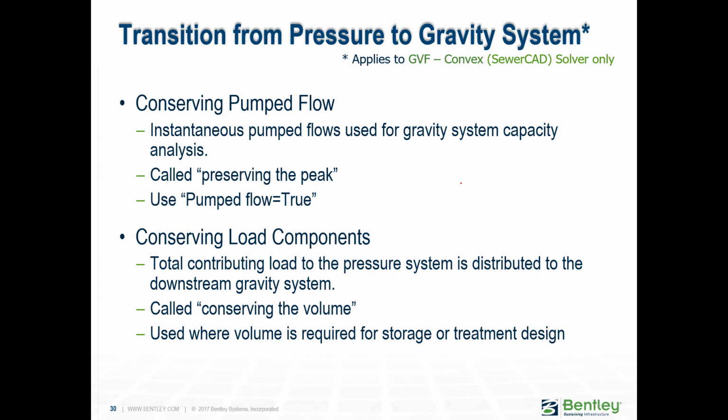Okay, the default is conserving pumped flows, which means it will assume that whatever incoming flow is coming into the wet well will be pumped out. So it just kind of ignores the pump. It says, I'm assuming that I will get a pump that will be able to pump it all out to my outflow.